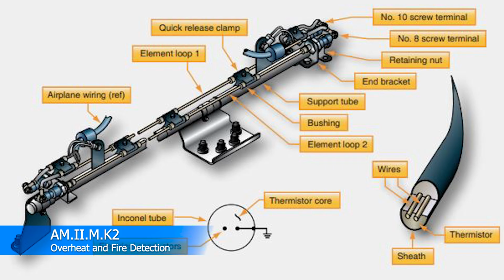You have these little cushion clamps, and they have a very distinct look. You'll know them when you see them. They're kind of brown. They almost look like phenolic, but they're not. They're actual little asbestos and Teflon cushion clamps that hold that thing on there, and you can see them right there in the middle of the system. You'll see these on large commercial aircraft engines, just like the JT9s, and they're pretty easy to pick out.